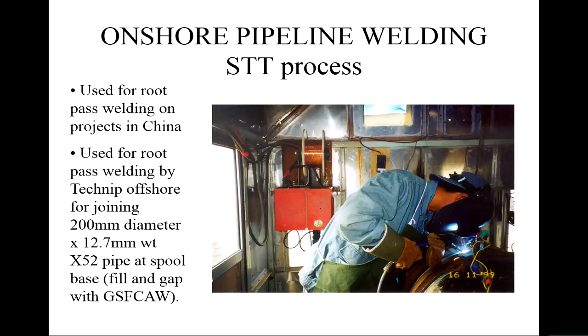There are some other types of welding processes that have been coming along more recently, and they've been driven by the fact that we can actually control the power application cycle in the power supply. So with modern solid state power supplies, we don't have a continuous output. We can vary the output in current and voltage, and we can do different things. And surface tension transfer, STT, is enabled by the modern power supplies.